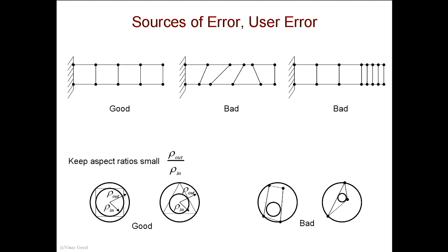One way to determine whether an element is a good element or not is to check it visually, or you can look at a definition I'll give you very soon. If I took this square, for example, for me this is a good element because it compares very well to the standard isoparametric element.